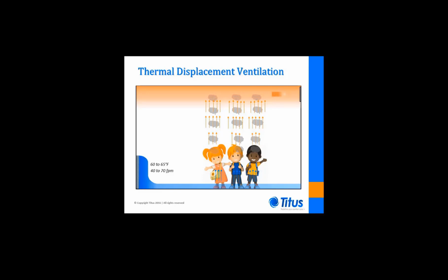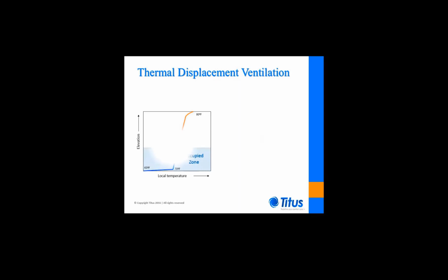Heat gains such as those from lights that originate above the conditioned air reservoir escape naturally and do not affect the amount of air required to condition the occupants of the space. This figure relates the temperature relationships for a thermal displacement system. Note the temperature gradients between the ankle and the return air levels. This gradient forms as a result of space heat gains that occur above the supply air layer.